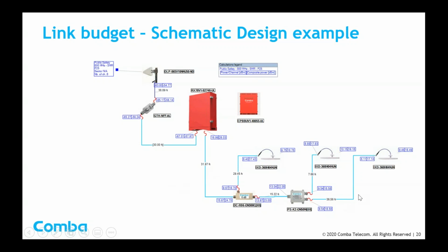On the uplink side, when that radio is talking to the service antenna, all these components again cause some loss, so that needs to be calculated so the designer knows he's going to get X amount of input to the BDA, and that's going to turn into X amount of signal to the tower.